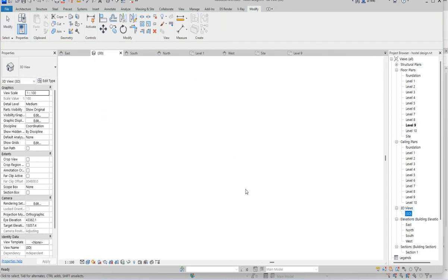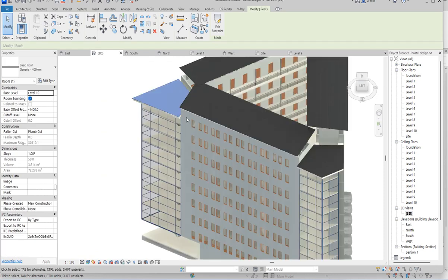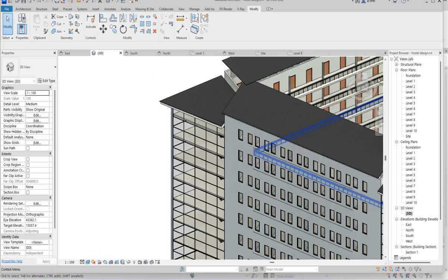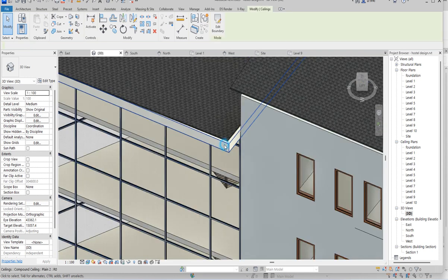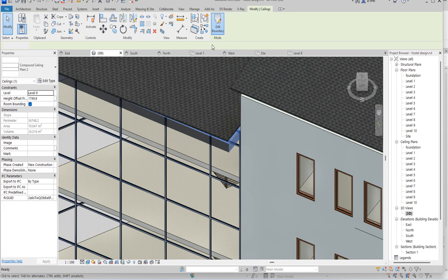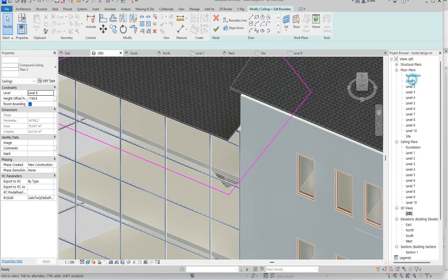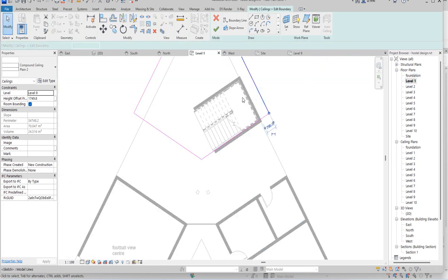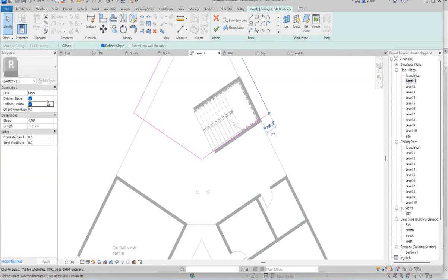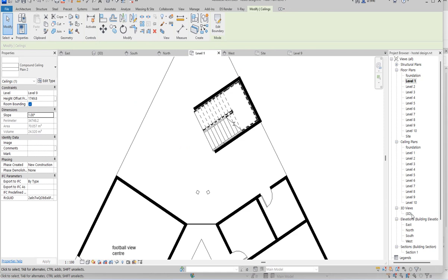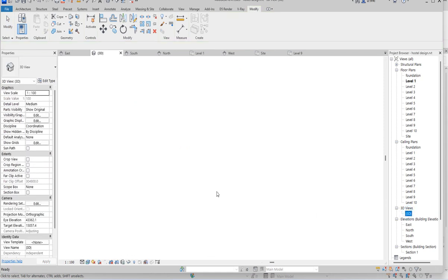So check it in 3D and see the coordination of what we have created. So finish. So this one has what you need to have as well. So click here, you can have define slope of that one too. And then you go back to this and you see define slope. So define slope and you press 1. That's 1. So everything will be aligned and then parallel with what we have created.